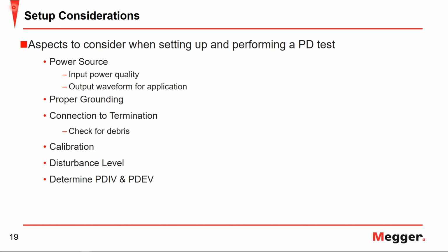And then as you're going down in voltage, your extinction voltage is also found to be above operating voltage. So now you have the confidence that even if you were to have a surge, a transient of some sort, that if partial discharge were to start taking place, once it settles back down to operating voltage, that partial discharge would cease to take place.